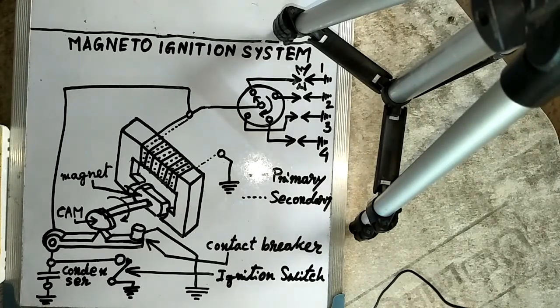The main disadvantage of the high tension magneto ignition system lies in the fact that the wiring carries a high voltage, and thus there is a strong possibility of causing engine misfire due to leakage. To avoid this, the high tension wire must be suitably shielded. The development of the low tension magneto system is an attempt to avoid this trouble.